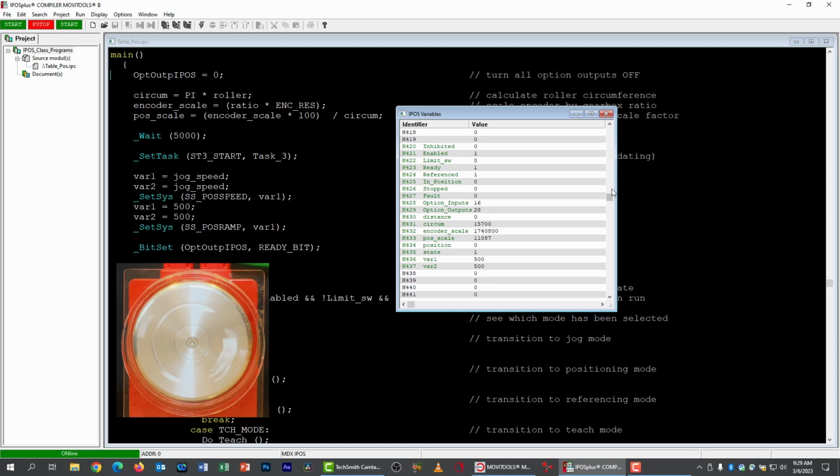Let's turn both on just to see if it halts. And it definitely does. I'll turn one off now, and it's spinning again. Let's turn them both off, see if it stops. Yes, indeed it does. It appears that that functionality is good. Now let's go ahead and try some of the abrupt stops. Let me get the drive running again, and I'll remove controller inhibit, and it stopped abruptly, and you can see the state went to 0, which is dispatch, which it's supposed to do.